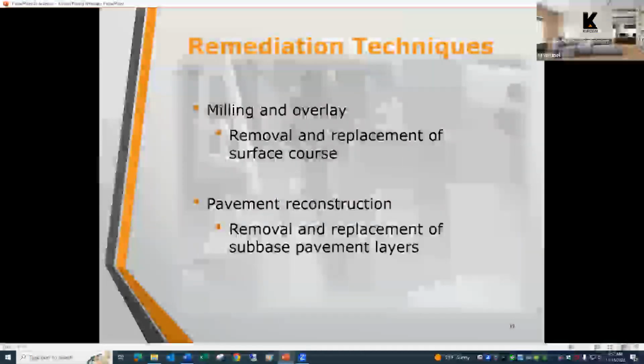So when we do those pavement core samples, we're looking for the point where, after they mill off that 2 inches of pavement, is there enough asphalt left to be a proper stable sub-base for the new pavement that you're putting on.